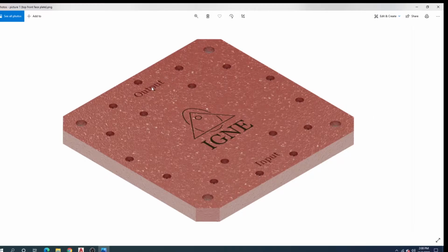All right, so this is the top faceplate without the terminals or anything. You can see the output terminals are here. Input terminals will go here and here. This material is made from phenolic. Actually, it's a G9 glass cloth woven phenolic. The reason I picked this material is because of its high temperature resistance characteristics.